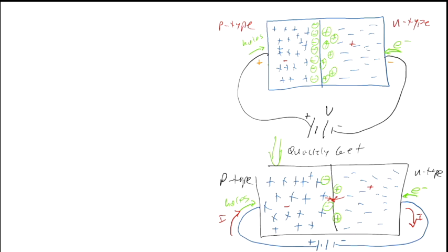So we'll have current across this diode due to both majority and minority carriers, but there are so many more majority carriers than minority carriers. We may have 1e17 majority carriers, and we may have 3,000 minority carriers, right? So the vast amount of the current flowing through here will be due to the majority carriers, and it can be a lot of current. And we call this forward bias.